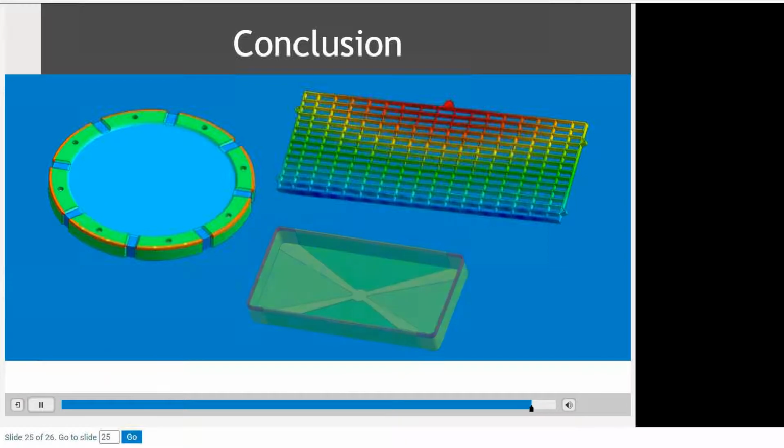An important difference between flow leaders and flow restrictors is that flow leaders always start at the gate for proper processing, while flow restrictors do not. As we've seen, both options can be used to design and mold high-quality parts. Okay, just to recap, flow leaders. This is a part from the previous lesson that I have not shown you here in this webinar series. But again, flow leaders start at the gate and go to the outside to really promote flow. That's usually how that works.